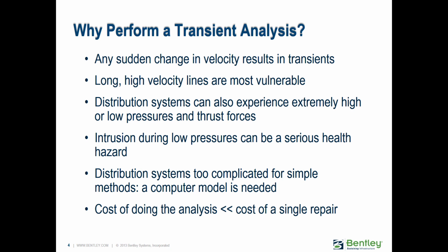So you definitely need to check and do a transient analysis anytime you have a sudden change in velocity or momentum. It's definitely a good idea to do a transient simulation and check to see if it's going to cause something that will be a problem, and whether you need to do something to mitigate that.